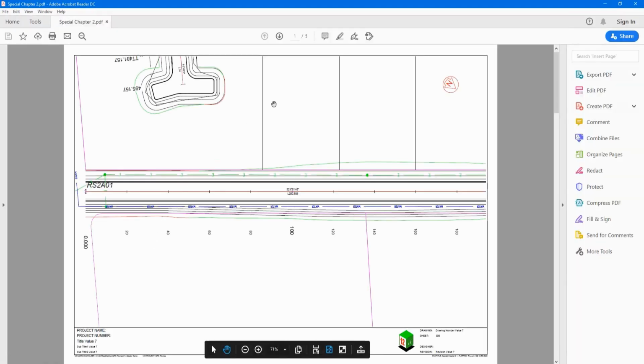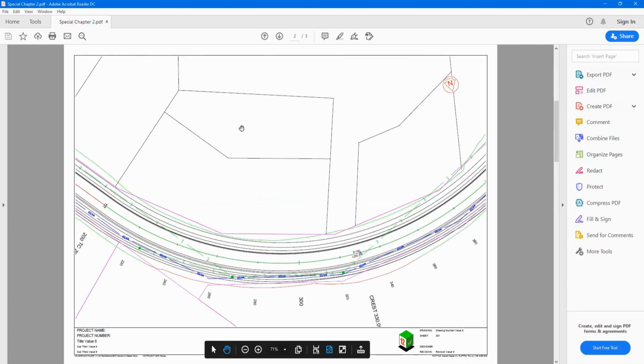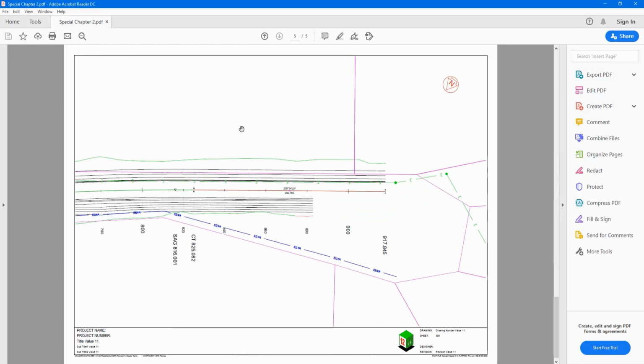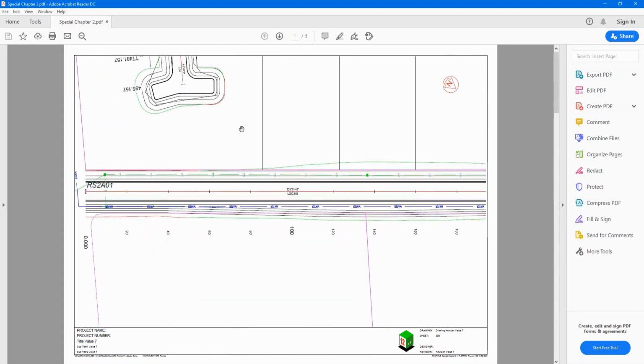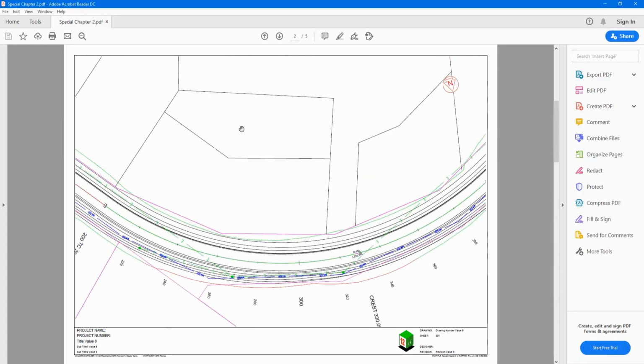Right, that's completed, and you see I have 5 sheets which match the 5 plot frames. I have my north symbol automatically orientated to the sheet or the plot frame position, and I have my drawing numbers or my sheet numbers starting at 300. So if I scroll down through those sheets, okay, you'll see that north point automatically orientate for the orientation of the plot frames, and they've just been very quickly placed along an alignment.